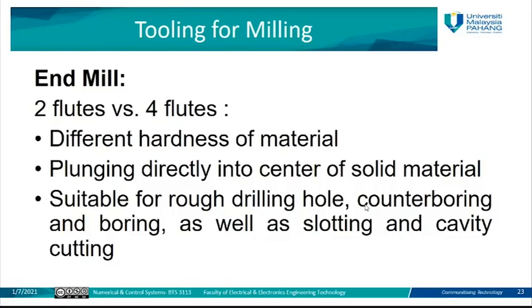I think we already saw such a tool previously in some examples for the G code when they said end mill. In the end mill here, we have two types, either two flutes or four flutes, depending on the hardness of the material for each type. This type of end mill can plunge directly into the center of the solid material, suitable for rough drilling. It is also suitable for some hole operations like contour boring and boring,